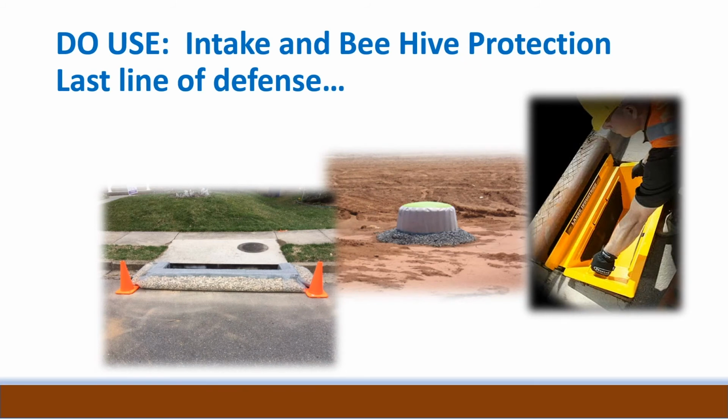All storm drain inlets and streets near the project need to be protected, as well as beehive inlets. Storm drains can be protected with external practices or drop-in inserts. External filter protection is typically used for beehives.